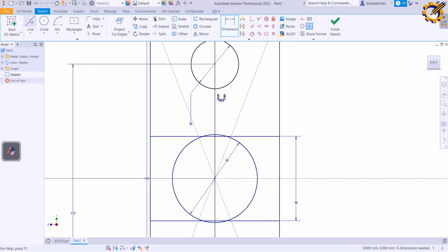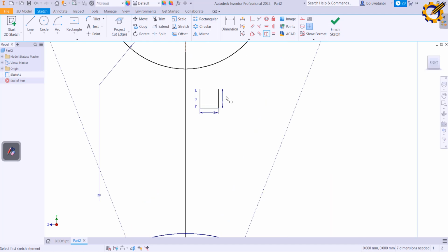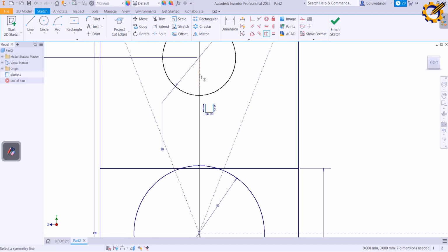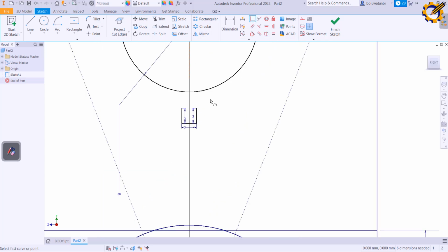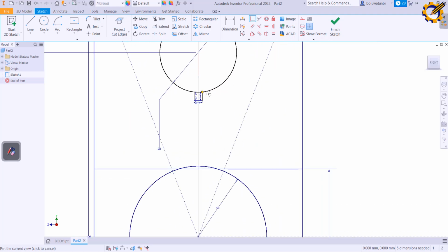So I'm going to create a hidden line in the middle of the circle right here like this. Then I'm going to use my symmetric constraint, 1, 2 to this hidden line here. And with my coincident constraint, attach this to this like this. You can see, simple as that.